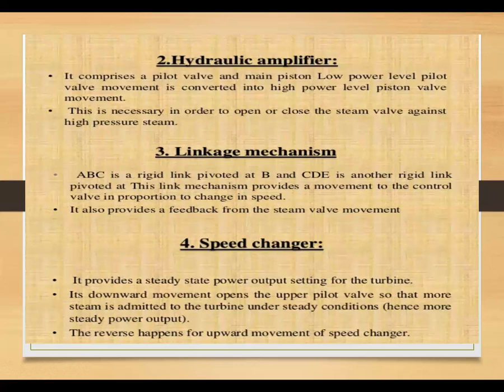Hydraulic amplifier. It consists of a pilot valve and main piston. With this arrangement, a low power pilot valve movement is converted into a high power level movement of the oil servo motor piston.